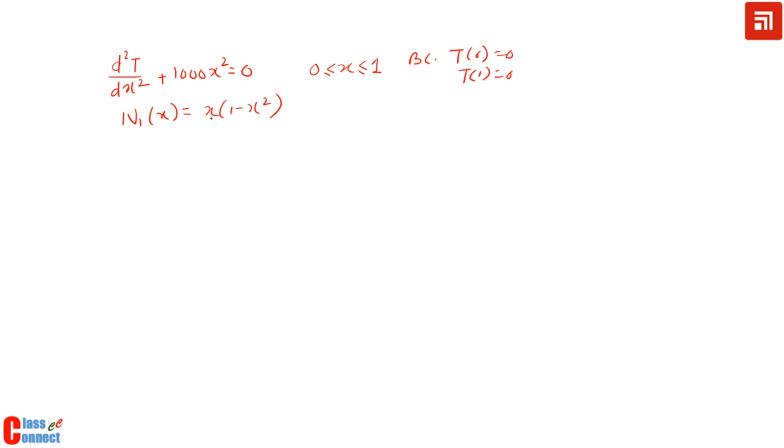So the trial function should be continuous and differentiable up to the highest order present in this case. That is why we have taken this trial function. It is given in the problem, though we have different methods in the finite element method that we will be discussing later on, such as how to select a trial function and how to find the expression for it.